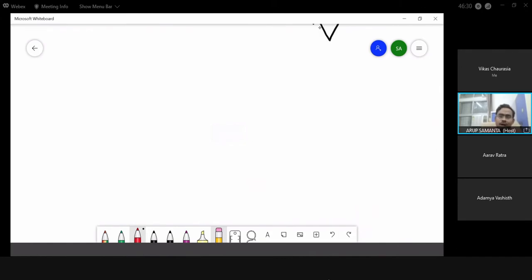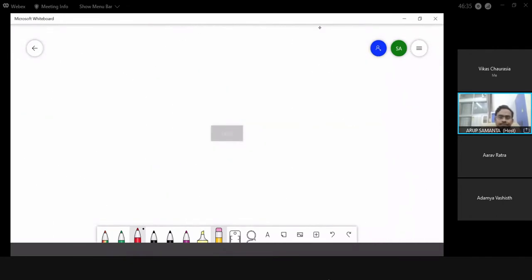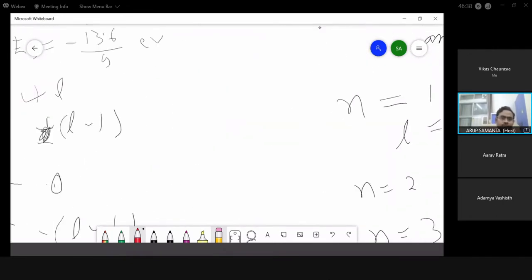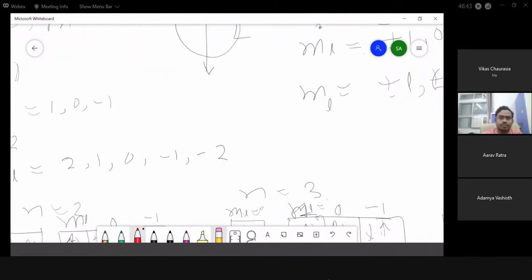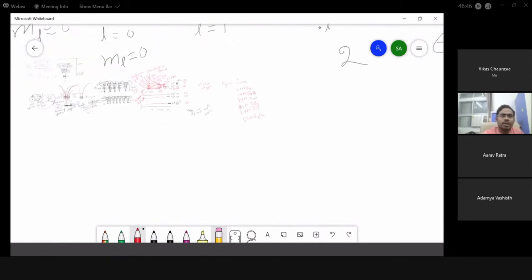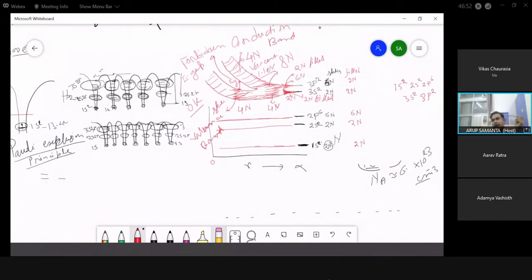The important thing is that this gap is very important. The upper band valence electrons, the outermost shell electrons in the solid form, meaning when the atoms are close to each other, split into two bands. Why do we call this a band? Because this band contains 4n electrons. But these are also all discrete energy levels, 4n discrete energy levels.